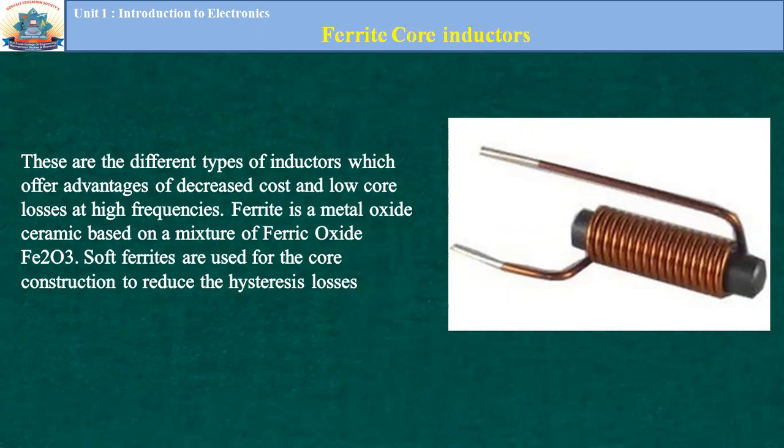Ferrite is a metal oxide ceramic based on a mixture of ferric oxide, Fe2O3. Soft ferrites are used for the core construction to reduce the hysteresis loss. It is used for high frequency applications, RF applications, and intermediate frequency applications.